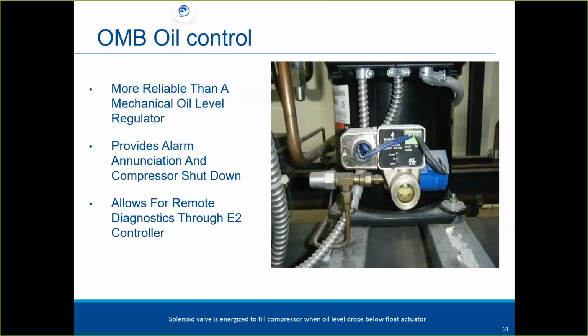And if you work in geothermal, I did quite a bit of that back in the day. You see a lot of thermistors on geothermal units. And basically, as you all know, I don't need to tell you technicians this, it's just clipped on the refrigerant line detecting the temperature, but it's sending it back electronically as opposed to pressurizing that bulb, okay? Good question.